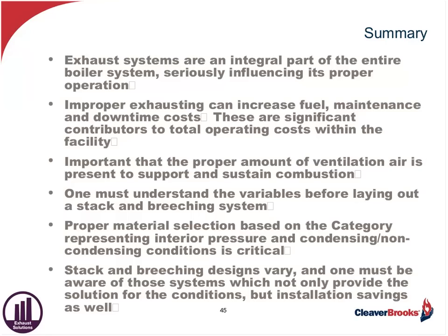Okay. In the scenarios that you gave, Chuck, both examples showed an open chimney top. The question is, what happens when it rains? Well, when it rains, in these particular cases we didn't have a cover on it. The inner wall is stainless steel, so corrosion won't be a major factor. But both systems that we show also have drain tees installed at the bottom of the stack for drainage of any condensate or rain that may collect in the stack.